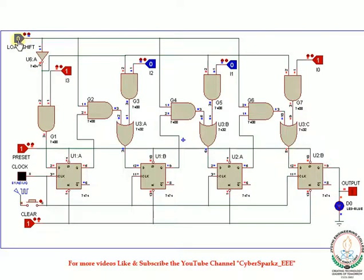So in order to do the shifting operation, change the mode to shift mode, that is 1. Now you have to provide the remaining 3 clock pulses to obtain the remaining 3 input bits. For the first clock pulse, your output will become 0, and for the next clock pulse also your output will become 0. The next clock pulse also gives 0, and the last clock pulse will give you the remaining last bit, which is 1.